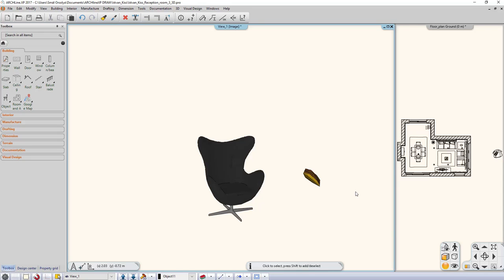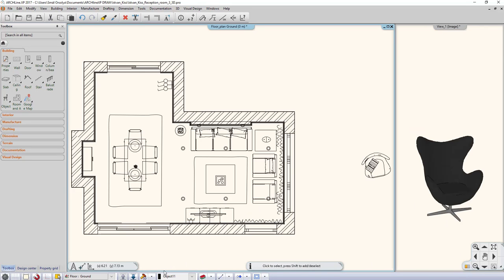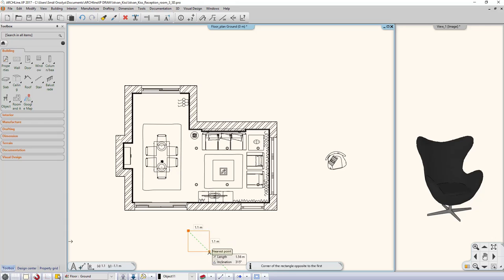The unnecessary 3D shapes must be deleted from the plan. First, display the 3D shape in the 3D window. We do this in the following way. Activate the floor plan window. Select the Create Cutaway 3D View command. With the help of this command, we can rebuild the selected part of the plan.